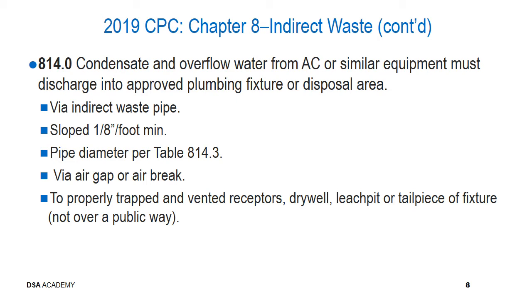It's acceptable that these discharge via an air gap or an air break into the plumbing fixture, and that these must be piped to a properly trapped and vented receptor, a dry well, a leach pit, or the tailpiece of a fixture.